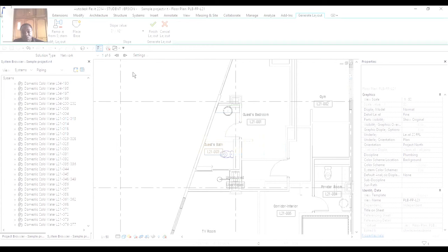The network logical reasoning is based on Revit creating a bounding box around all the fixtures within the given system, then using a central line, here the blue one, the main pipe, and interconnecting it to the rest of the plumbing fixtures using the secondary pipes that are green on the screen.